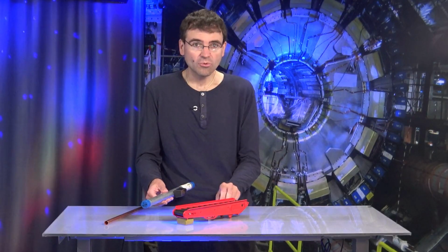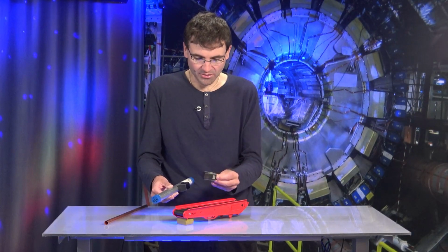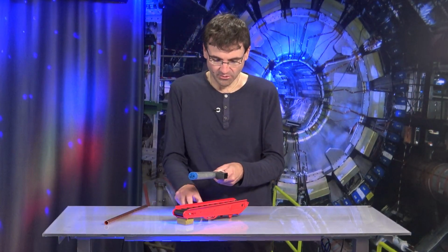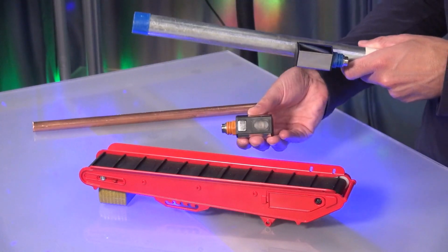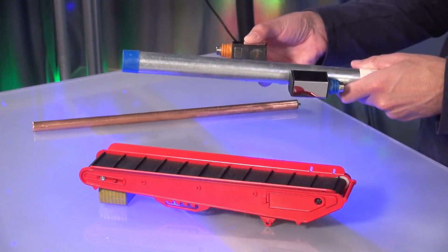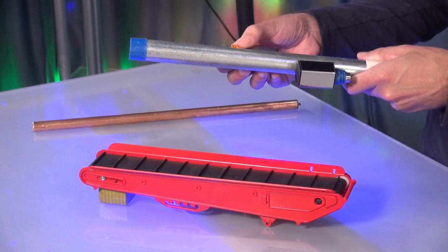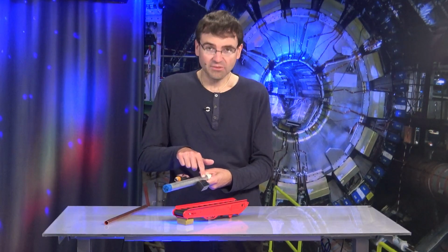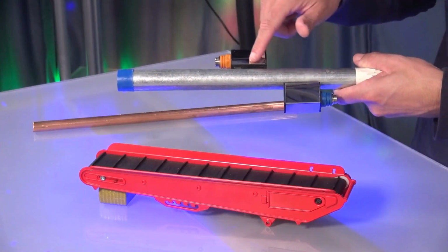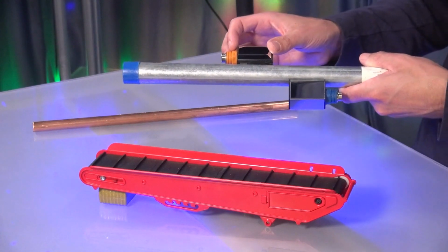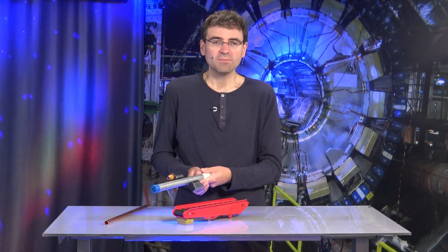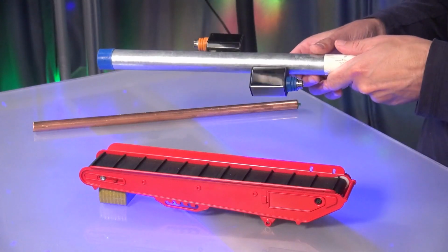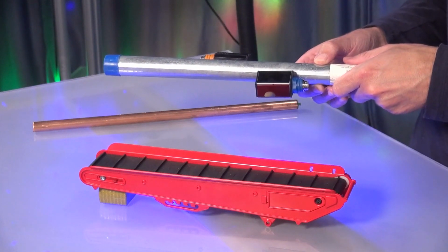And of course, we do not just need a transmitter, as it would not make any sense to send something and then not receive it, which is why we will also require a receiver here. That receiver looks very similar to our transmitter in this case. And it also works in the same way. Again, we have a piezo crystal and I attach it a little further along the pipe. And now the signal is transmitted. It penetrates the pipe and will then be received again a little further on. In this way, through this measurement, we have determined the transit time of the signal through the medium.